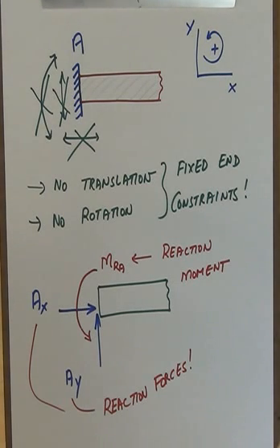And you see that if I have a fixed support, then there is no need for any other support, because the fixed support itself has three unknowns. And you know that in 2D rigid body equilibrium, you have only three equations of equilibrium. Sum of forces in the x and the y directions equal to 0, and then sum of moments about any arbitrary point is equal to 0. So I have maximized the number of unknowns to begin with, and so I do not need any other kind of a support if I have a fixed support on a rigid body.